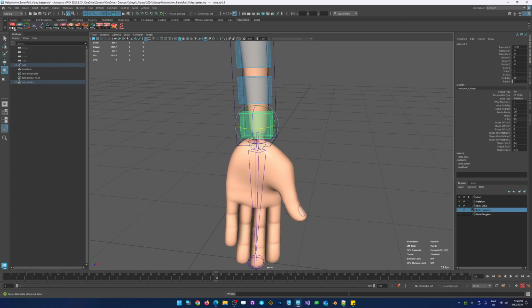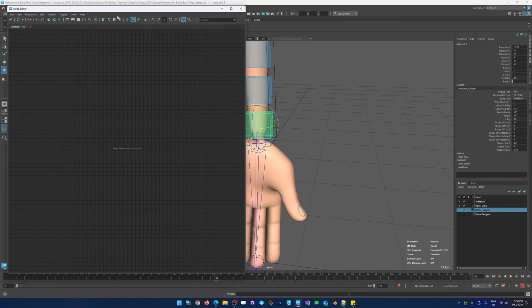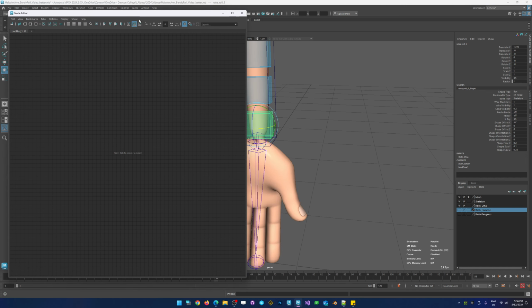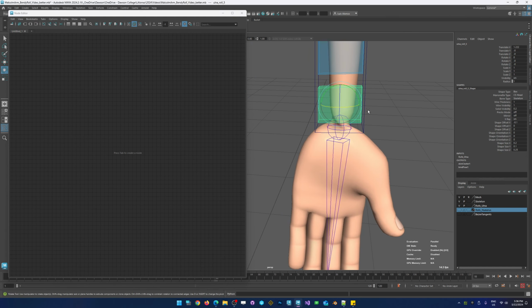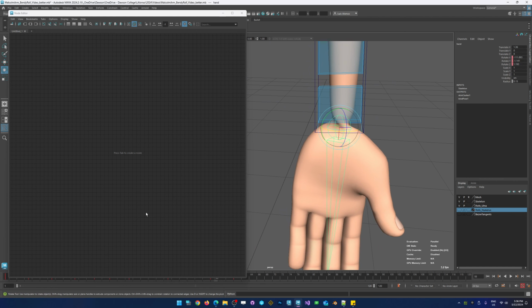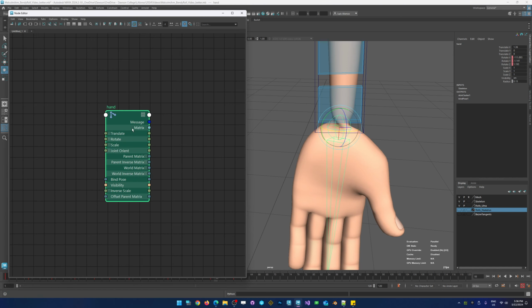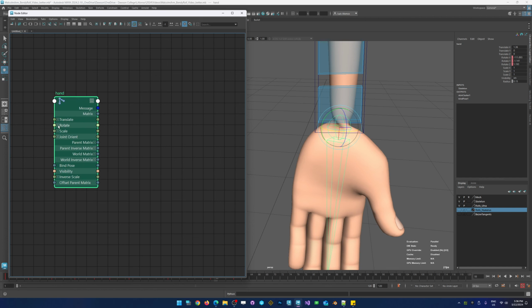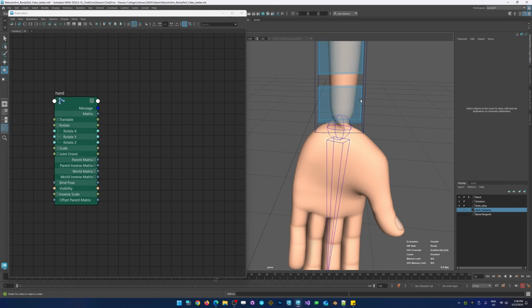Okay, so if I go into the editor here, and by the way, you can do a lot of rigging just with the node editor, frankly. There's a lot you can do with this. So if I take this bone, which is going to be my reference bone, or the bone we're using in order to calculate everything, and I press a little plus sign here, I'm going to have the hand, and we're going to have the rotation values available, so we can pull them out and connect them directly to the rotation value of this bone here.